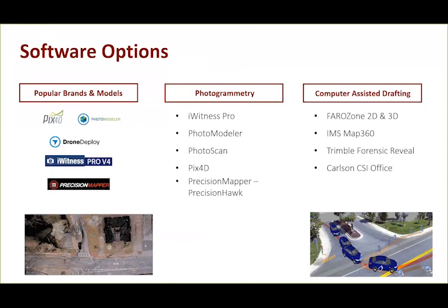Yeah, I've used DroneDeploy. DroneDeploy is averaging about $1,000 a year for the subscription, and about a year ago I started playing around with Precision Mapper, which offers a free service where you can do 5 scans a month. Like you said, you definitely have to pay attention to your overlap for your accuracy, though. So know the limitations of the software that you're using. Would you agree? Yeah, absolutely.